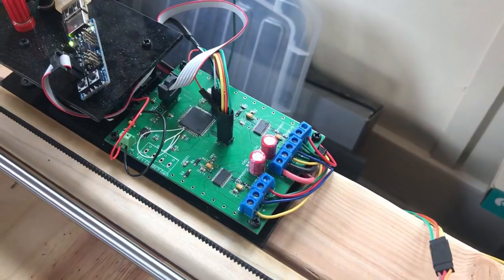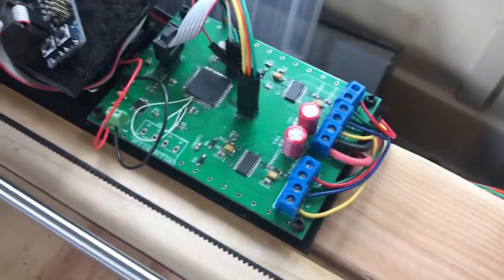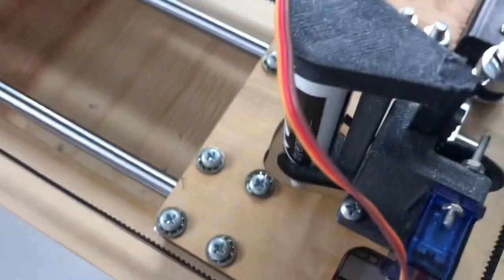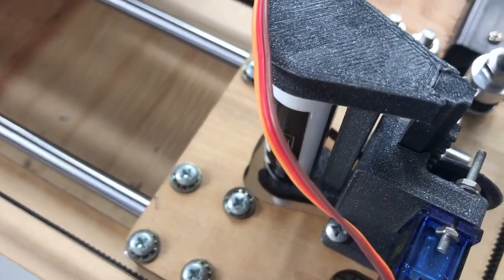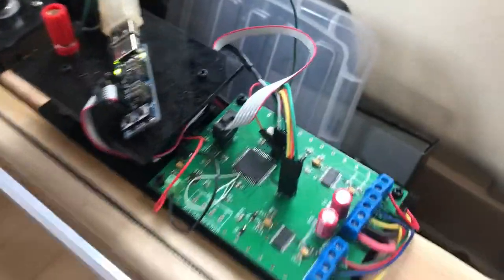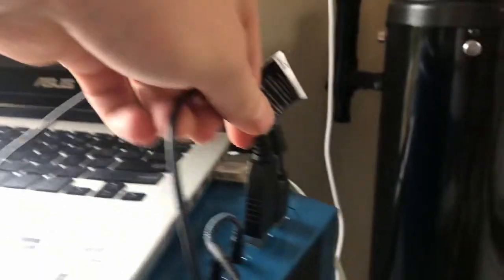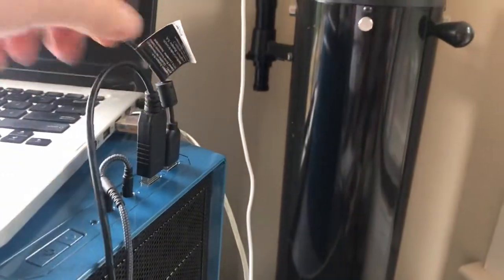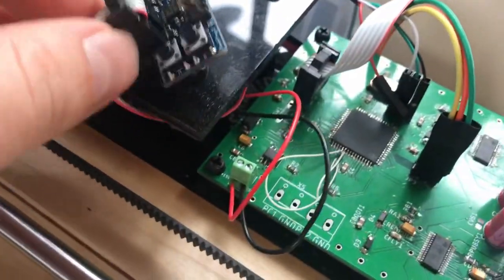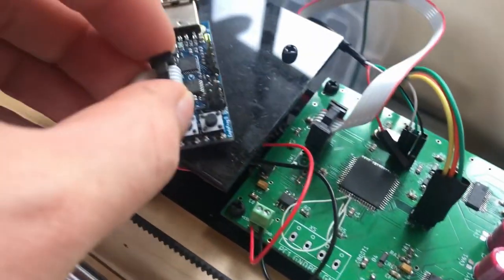So here is a better video of some of these interconnects. You'll see the header pins that we use to connect the servo over here simply plug directly into the circuit board. You will see our UART header pins over here. Those actually connect up to this extremely cheap Prolific knockoff that I got years and years ago into the computer running MATLAB, which itself is connected over simple USB to this old Logitech webcam that I also got years and years ago. And also here you'll see our PDI port, which is connected to our programmer right here.